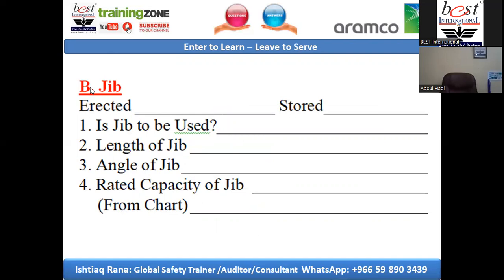Then specifically, we have to talk about the jib, erected or stored. A few more important points relevant to the jib make up portion B. Number one, B1: is a jib to be used? What is the length of the jib, the angle of the jib, and the rated capacity of the jib? Of course, we have to look into the chart for the rated capacity of the jib.